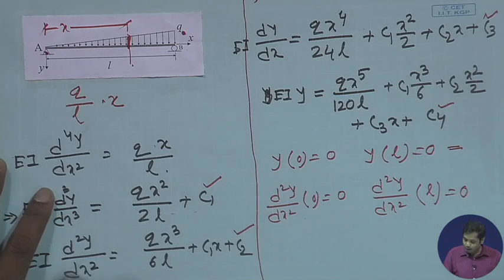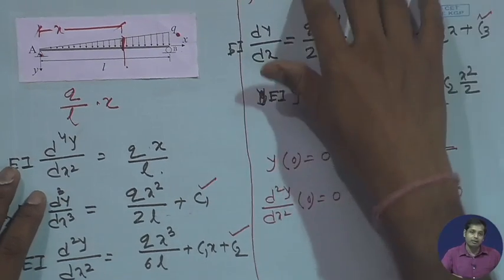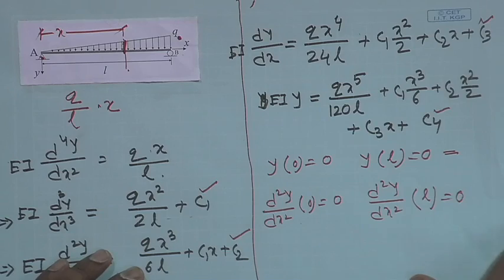Now, in any boundary value problem, the governing equations are given along with some boundary conditions. There are 2 kinds of boundary conditions we can have. One boundary condition is applied directly on the primary variable. For instance, here the variable is deflection. Those boundary conditions are called essential boundary conditions or Dirichlet boundary conditions. Another kind of boundary conditions are specified on forces, for instance, the moment is 0 at a given point or moments are specified at a certain point. Those are called Neumann boundary conditions or natural boundary conditions. So, here 2 different kinds of boundary conditions are given, right.